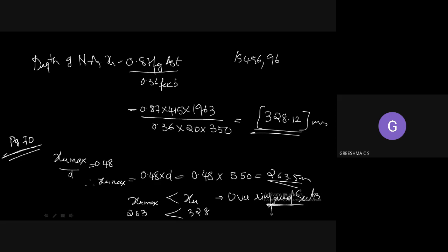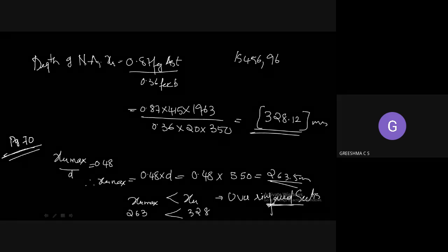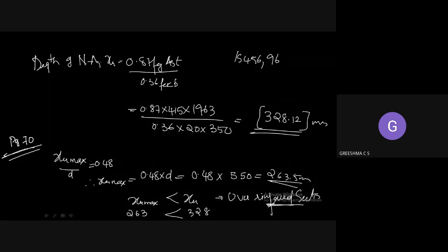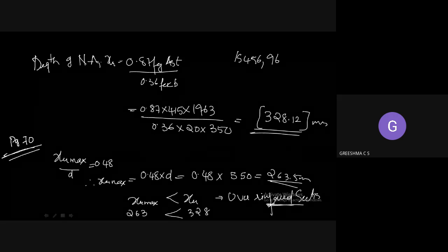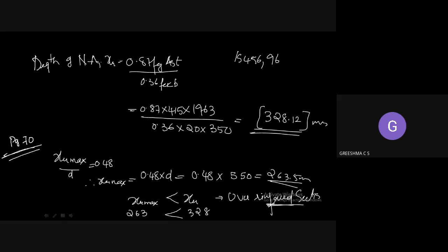Just now I have shown you the IS 456 page 96 in the constants. The first equation, the 0.87 fy one, is for the under reinforced section. The second equation is for the over reinforced case. So you have to take that equation, substitute the values and find out the moment of resistance. All of you please take down that value.